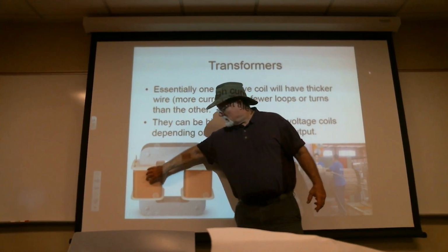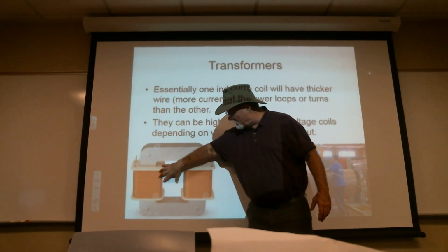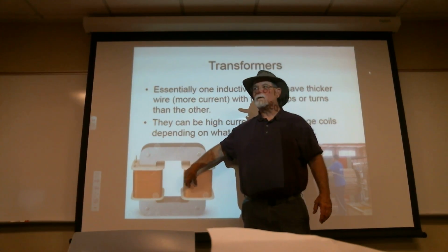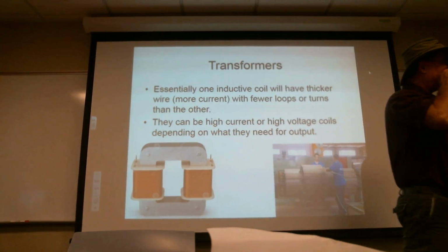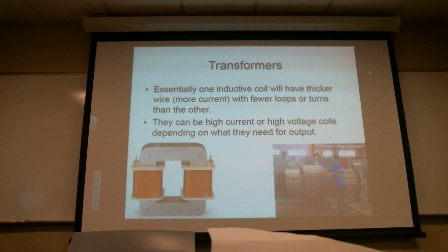And each time it's built up in here, it's going to cut across here and cut back out. The magnetic field will cut across a much bigger wire, which has fewer turns, but much less resistance. Okay, so a lot more current can flow through it. So the output, the voltage will be dropped, and current will come out.